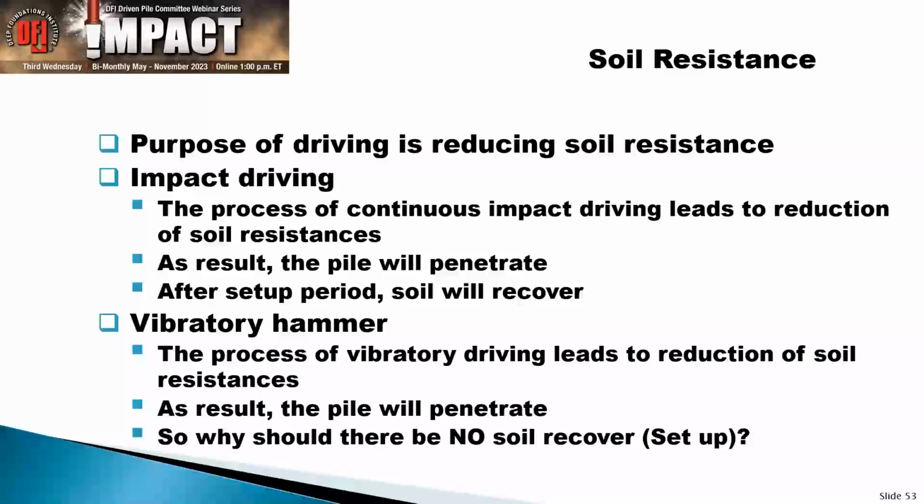Two comments on that. Why do I say vibratory driving is not the same as liquefaction? What happens with liquefaction is that the water pressure takes over, and you no longer have an effective soil pressure, and therefore you have liquefaction of the soil. Well, there have been plenty of tests done where you have completely dry soils, and nonetheless with vibratory driving you can get your pile into the ground, and therefore it cannot be liquefaction.